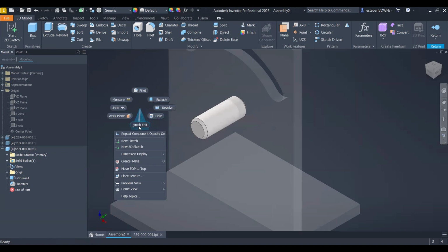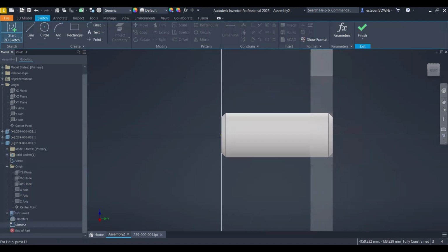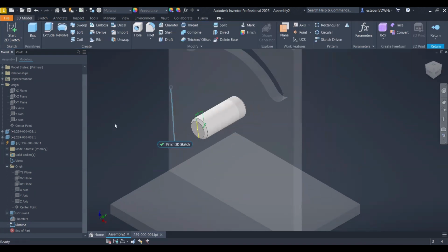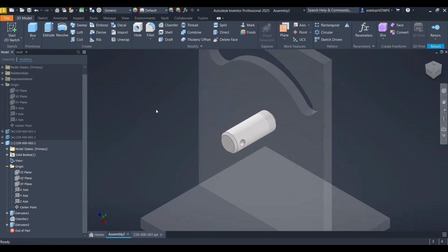Okay, so I will create a sketch over this plane, and let's say that, well, yeah, why not? We're just going to make a hole in here. It is missing one constraint. I will click here in constraints. If you want to see how to 3D model, I have a video for SolidWorks users that need to try to migrate to Inventor. Here is the link, here at the top, so you can watch that video as well.